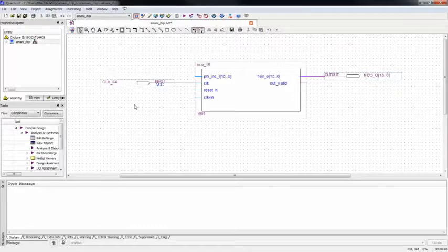So for example, if you wanted to connect to a high bandwidth DAC and create an FM modulator, which we're going to do a little bit later in this lab, and you wanted it to be centered around 100 megahertz, you would probably want to sample at least the Nyquist frequency, which would be about 200 megahertz. So you would create a PLL or a digital clock manager for 200 megahertz. But for the extent of this lab, we're going to keep it simple, and we're going to use the 64 megahertz oscillator for you guys.